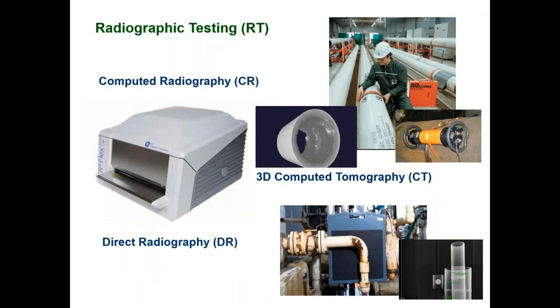One can do radiographic testing. This is a type of X-ray, if you will. It's non-destructive, but the caveat is you have to bring a big instrument in the field. But it allows you to use radiation or even types of high energy to produce an image that allows you to evaluate the extent of corrosion without opening up or even deciding on a replacement, not until you know the extent of damage.